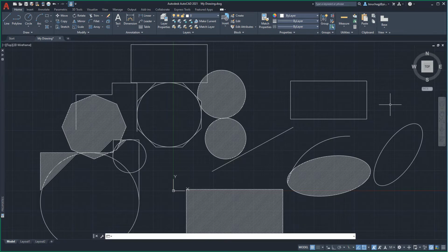After entering the stretch command and at the prompt to select objects, let's use a green back select pick window about the right end of this rectangle and press Enter. When prompted to select the base point, the user can actively select a grip point on the geometry or any relative point out in model space.